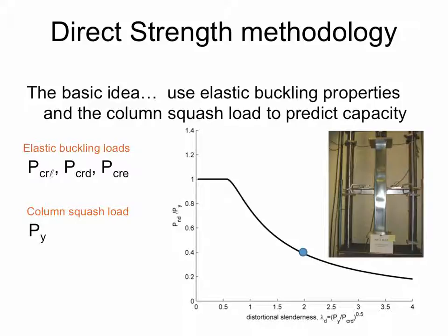Now, when we start introducing thin-walled structures, we have cross-sectional instabilities. So we have local buckling, with little half waves forming, or longer half waves like distortional buckling forming. But we treat the capacity of that distortional buckling limit state or that local buckling limit state in a very similar way with the design curve.